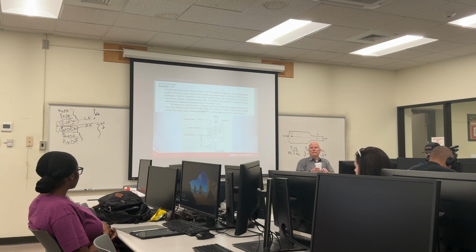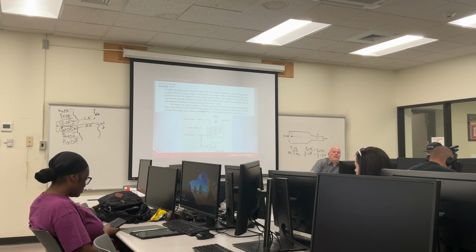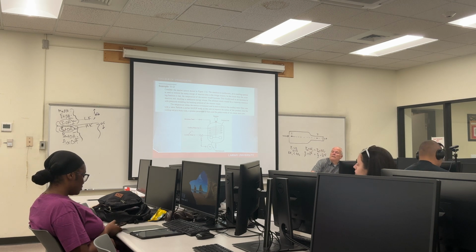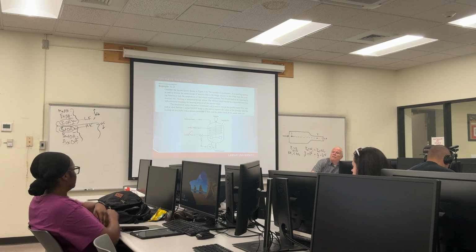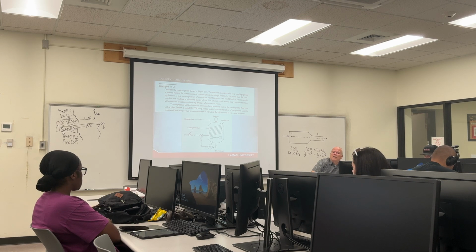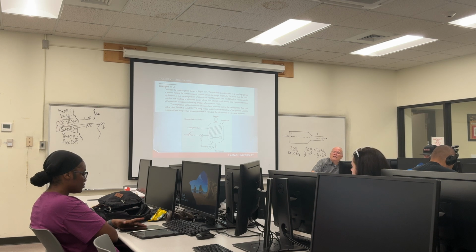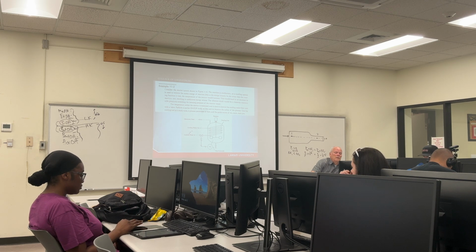Nothing cools down the reaction, and there's a runaway reaction. What happens if there's low flow? Same thing, only slower. Could be the same thing, right? And what if there's high flow? Could quench the reaction, maybe. Probably not going to cause you terrible trouble, but it'll quench the reaction.